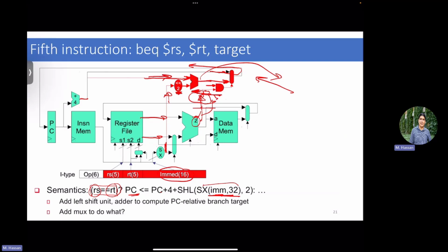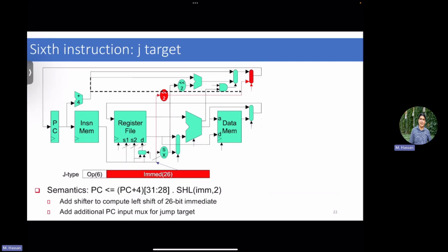And it's basically just concatenating them in RTL. So this dotted line here is just 4 bits wide, like 4 wires, taking the top 4 bits of the program counter from here and augmenting the 28 bits such that, if you want to write it precisely, you say that this is 28, this is 4, and this is 32. Make sense? Yeah. So a simple RTL concatenation.